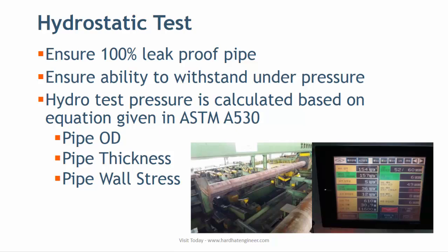For welded pipe, the test pressure should be held for the time sufficient to permit the inspector to examine the entire length of the weld seam. Hydrotest can be waived under certain conditions as set out in the standard.